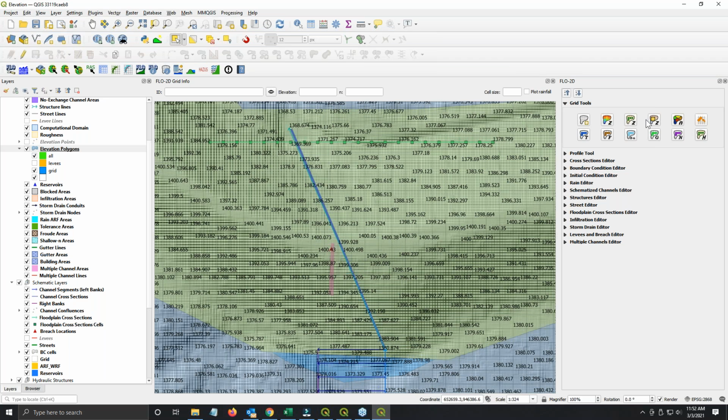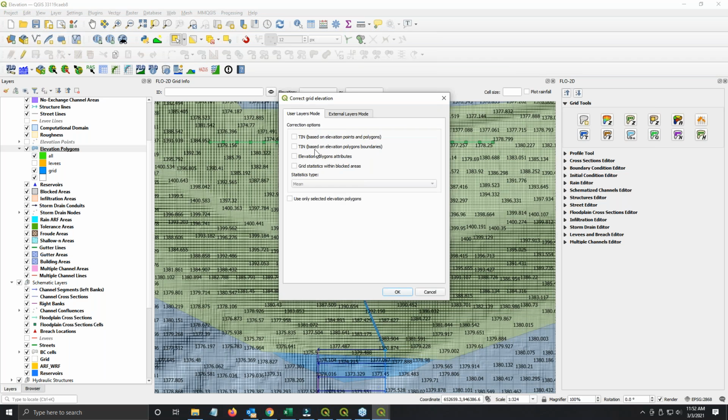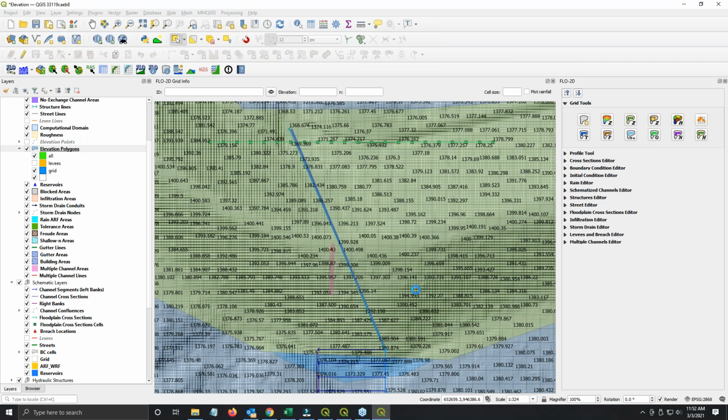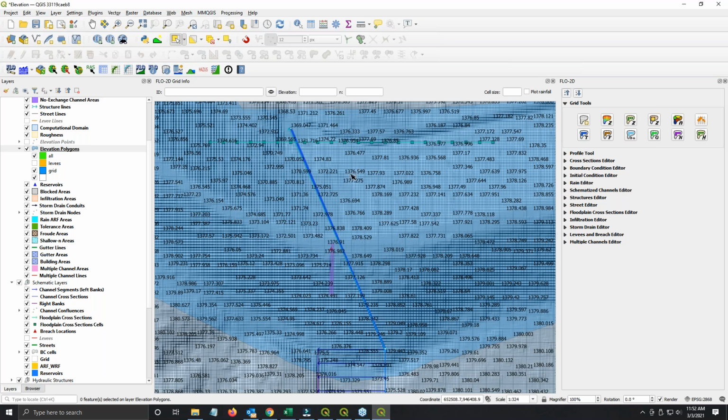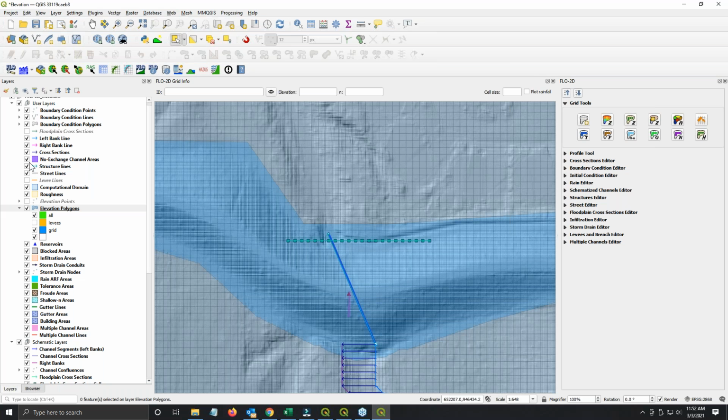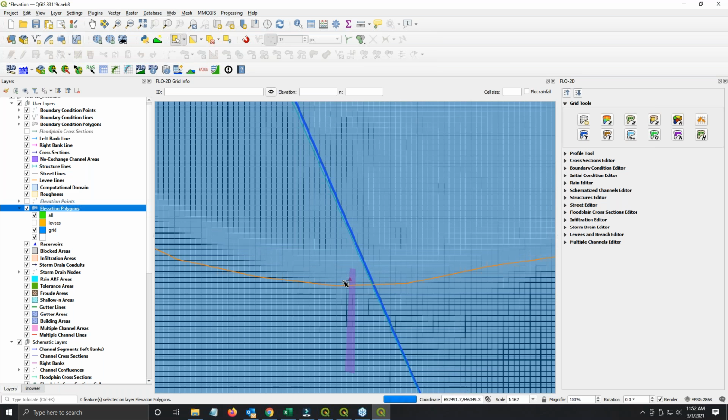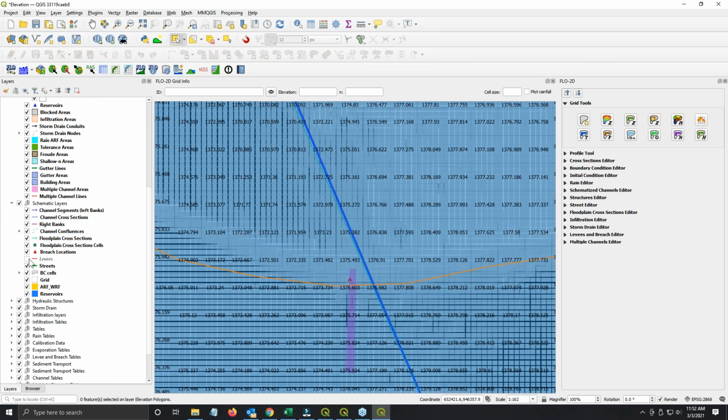So we apply the correction tool to the selected polygon. And once it's complete, I'll refresh the labels again. And you can see that what it's done is it's taken the dam out. So now if you set up your dam or your levee from the levee user line right here, this will become the elevation. And when you set your failure point, which I set right here, you can see your levees and you can see your failure point.